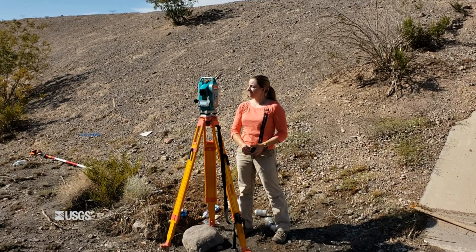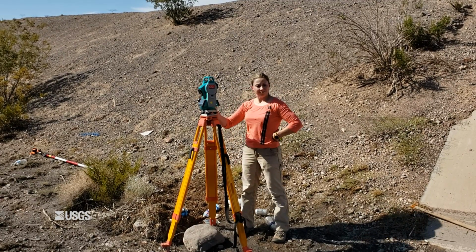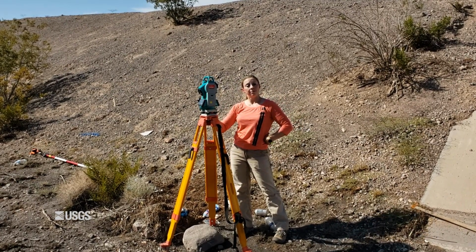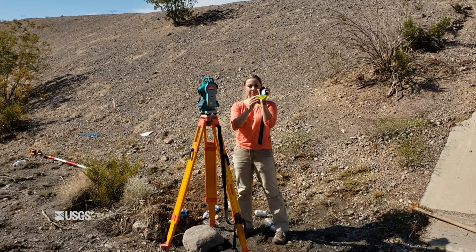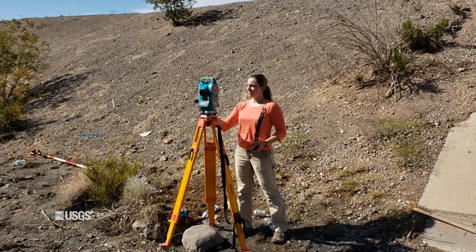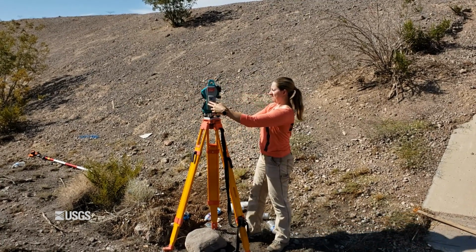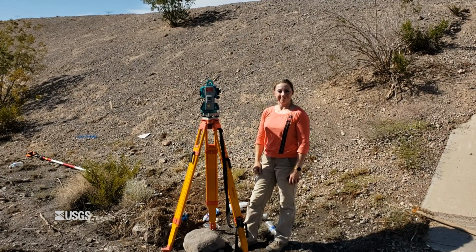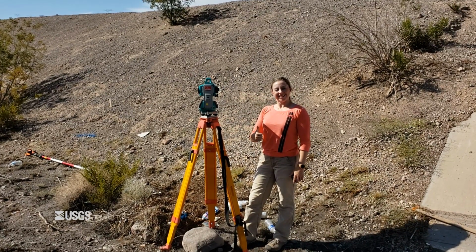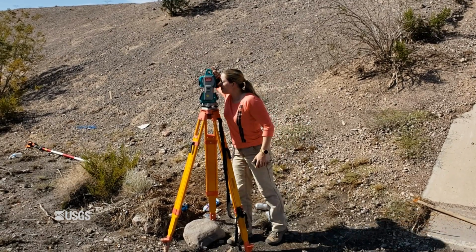However, we have options. It doesn't truly matter which direction you set to 0 degrees 0 minutes because we are surveying in an arbitrary datum. You have 3 main options. 1. Set the gun 0 to true north using a compass. 2. Set the gun 0 to upstream in the channel. Or 3. Set the gun 0 to the direction of the backsight shot. I actually prefer option 3 because I can check my angle at the end of the survey very easily, but all options are valid. Focus the instrument on the prism and take the backsight.